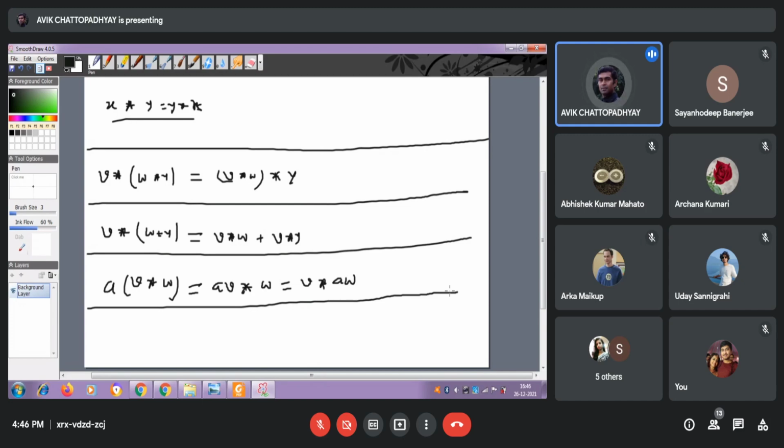And if both signals are shifted, then the convolved signal will be shifted by the resultant of that shifting. That means if one is shifted to the right and another to the left by the same amount, then effectively your convolved signal will not shift anywhere. It will remain as if no shifting operation was done before convolution. So that is related to time shifting.